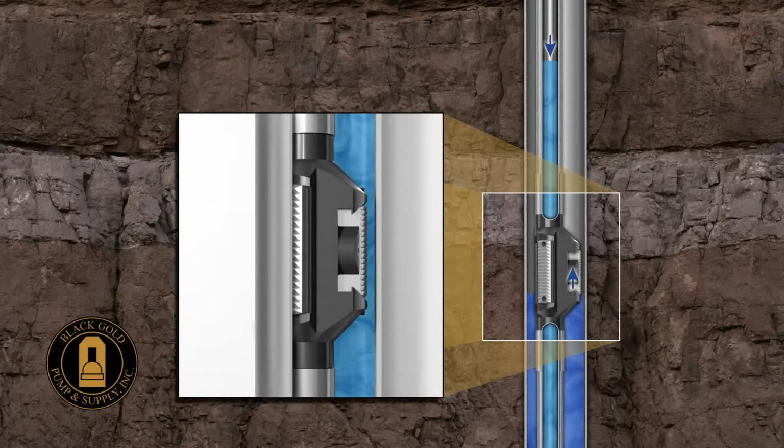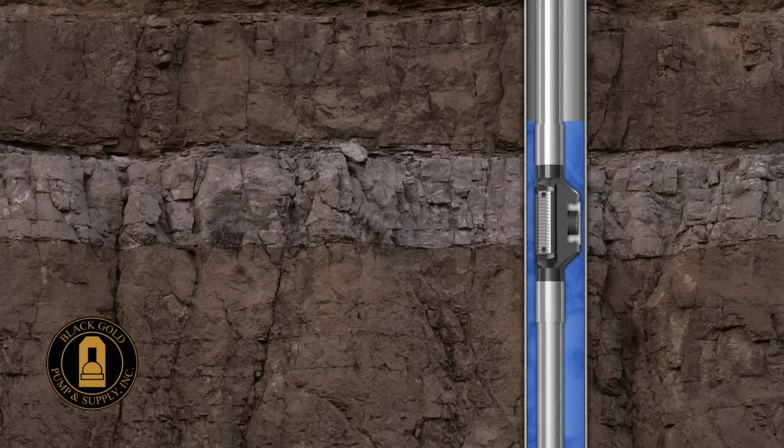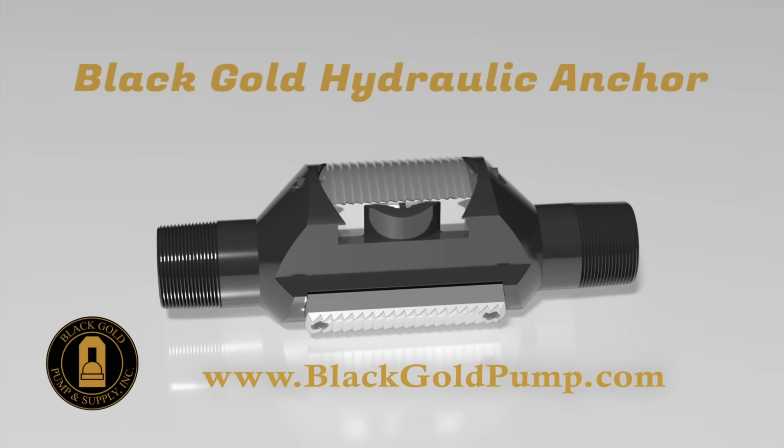Under normal circumstances, just equalize the fluid between the tubing and casing. Your hydraulic anchor is now unset and ready to pull. The Black Gold hydraulic anchor is simplifying the anchoring process and helping your well produce at its most optimal.